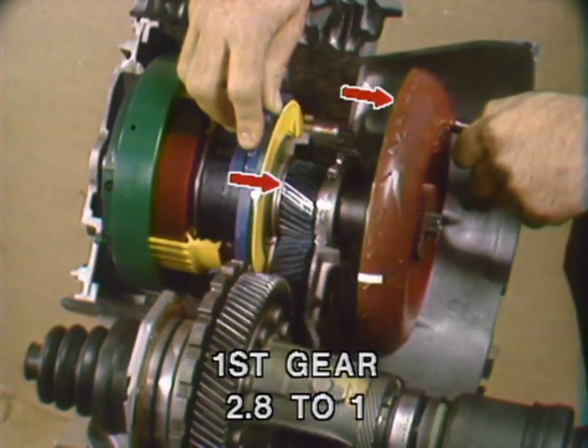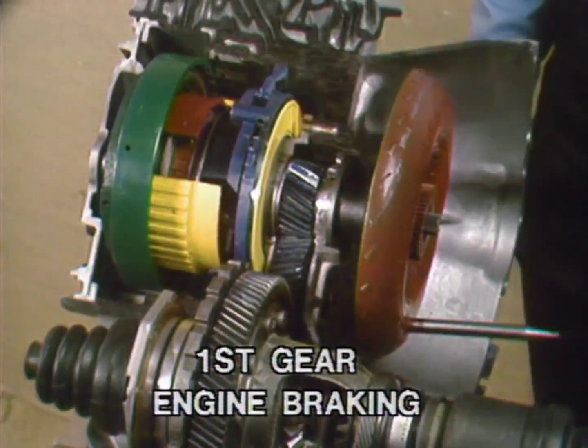The gear ratio of 2.8 to 1 can be increased to as much as 5.6 to 1 with torque converter at full stall. Remember now that what we've seen is freewheeling first gear. The one-way clutch holds when power is applied, but freewheels in the coast condition. For engine braking, as with reverse, we need the direct clutch. Let's look at engine braking.